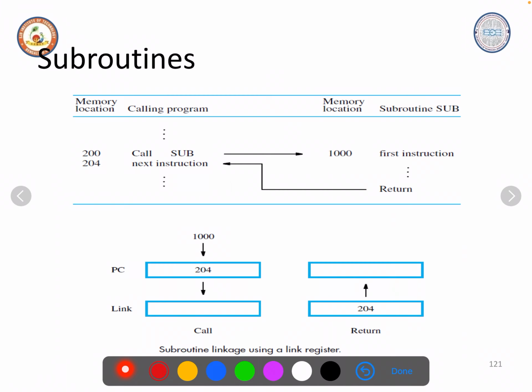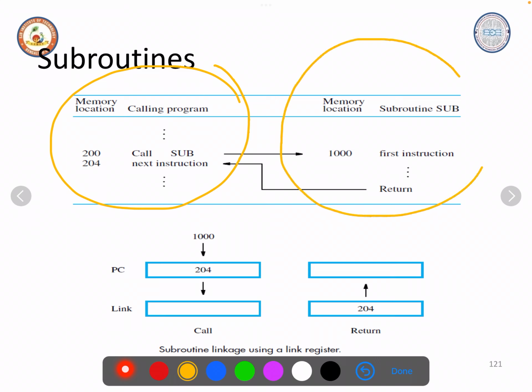This is an example. Suppose let us consider, this is a calling program and this is a subroutine. You are calling the subroutine at this location using a call instruction. This is a label of the subroutine. The address of the next instruction, usually PC is holding it. So first you need to store the return address. That means after completing this part, it has to return back to the main program. So this return address has to be saved. Return address will be saved in link register upon call instruction. 204 will be saved to link register now.